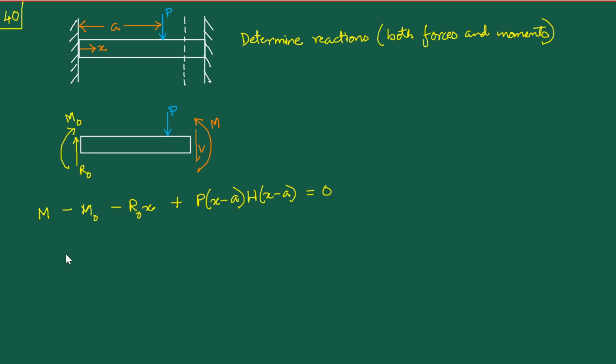So it's like this, that the deflection delta due to this R0 is going to be the integration from 0 to L of M by EI, del M del R0 dx, and you note that this thing is going to be 0 from physical consideration.